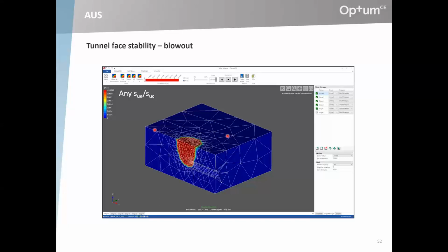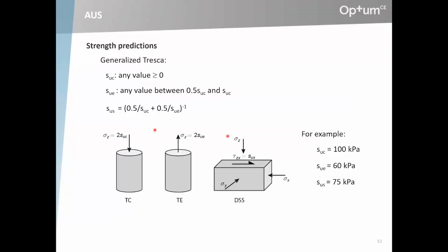In the collapse case, we have a lot of stress points in extension. In the blowout case, most of the stress points are in compression. So it's really problem dependent what effect an extension to compression ratio less than 1 has. If there's quite a bit of extension involved, so active earth pressure type problems, slope stability as well, then it can mean quite a bit. Otherwise, less so.